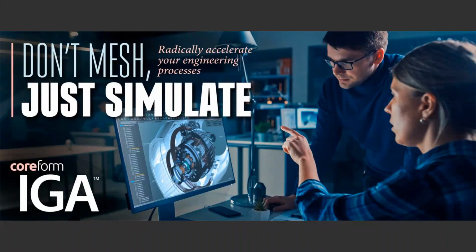But when you look at these things, if I can drastically reduce the number of quadrature points compared to traditional FEA, I still get linear systems of equations that come out. Those linear systems of equations are smaller. Yes, they're more dense, but they're smaller, and they have better conditioning. Whereas in traditional methods, as you increase degree, the condition number increases.